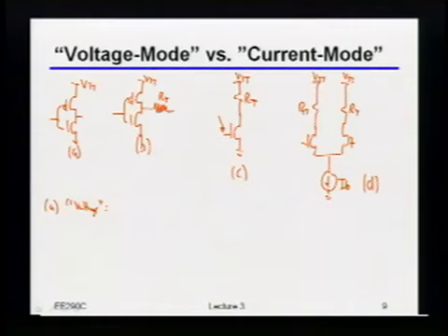So I claim there's actually sort of two things that's kind of implied by quote-unquote voltage mode in this particular driver here. The FETs are in triode. I mean, they're sized very large so that the resistance is pretty small. Okay, so you've said basically the FETs are in triode. So I'm going to twist that in a slightly different way. What you're basically saying is that the output impedance of the driver is set by the devices. Right? That's kind of what you're saying. It could indeed be low, by the way.